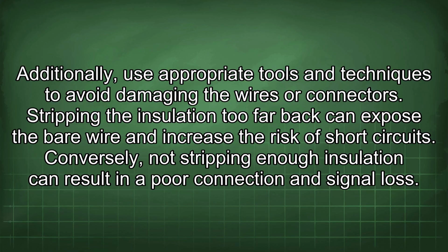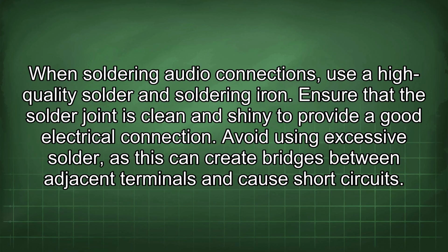Stripping the insulation too far back can expose the bare wire and increase the risk of short circuits. Conversely, not stripping enough insulation can result in a poor connection and signal loss. When soldering audio connections, use a high-quality solder and soldering iron. Ensure that the solder joint is clean and shiny to provide a good electrical connection. Avoid using excessive solder, as this can create bridges between adjacent terminals and cause short circuits.